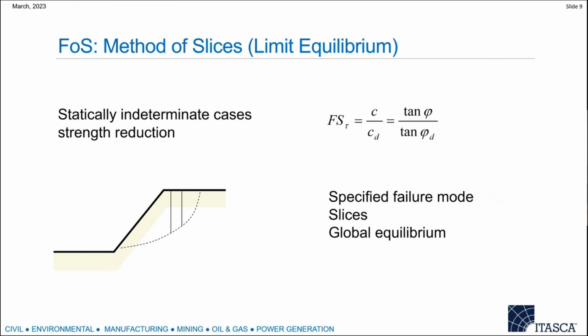Then we assume some forces of interaction between these slices, and then we take care of the global equilibrium, and then we can calculate the factor of safety.